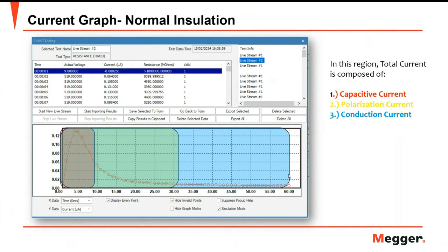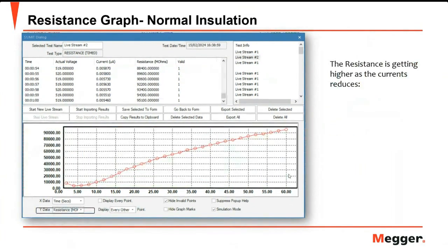The conduction current is present all the time up to the 60 seconds. Since we are only concerned with that current, we record the value at 60 seconds, because we just want to know only the conduction current. And with the leakage current, if you don't do the guarding, then the current you have at 60 seconds can include additional current from the leakage current.